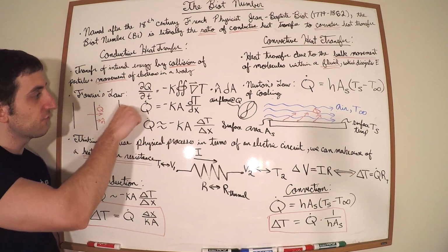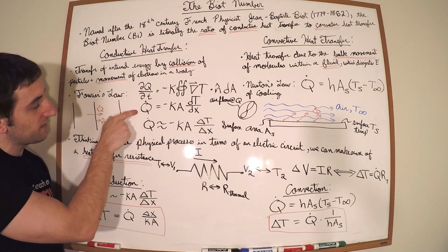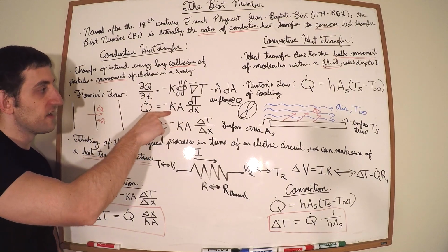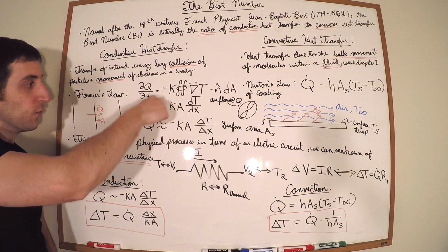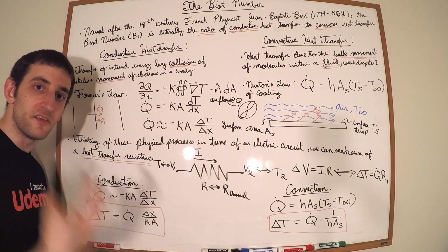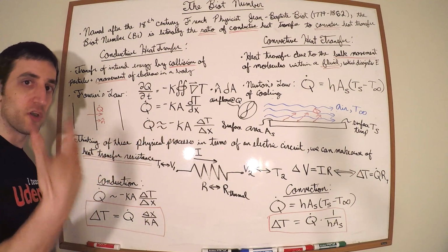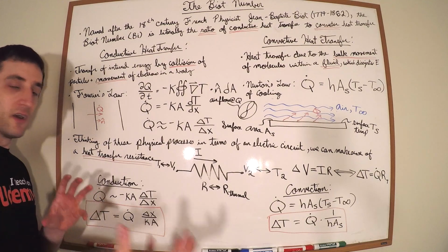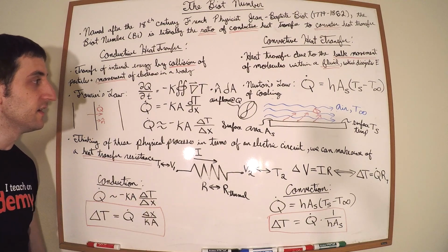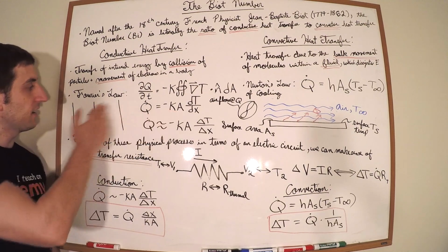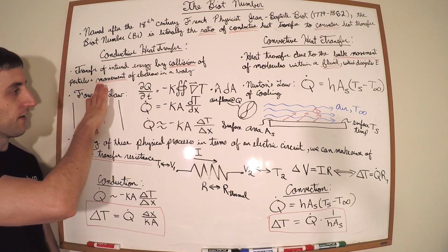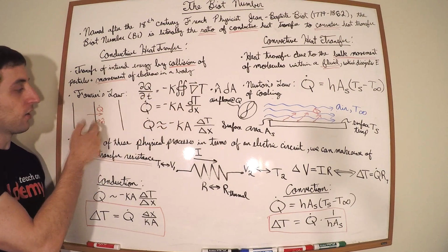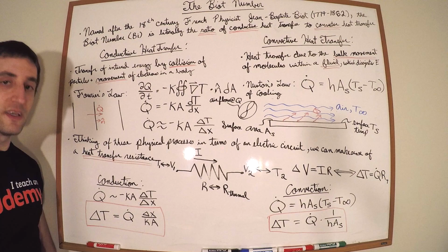where we take the heat transfer Q dot. It's basically this guy simplified down to there, new nomenclature. That is going to be proportional to this thermal conductivity, which is a physical property inherent in the material through which this is occurring. You can look that up in standard, I want to say dictionaries, but we have books that tabulate that information. And if you take that times the area it's flowing through, this surface area, and you take the derivative of the temperature across that boundary, you can get the heat transfer.